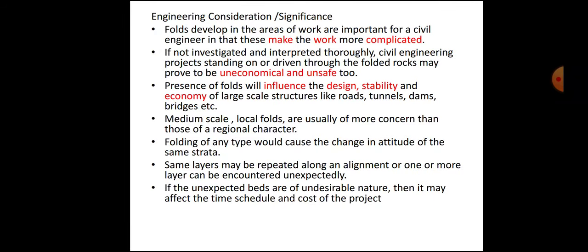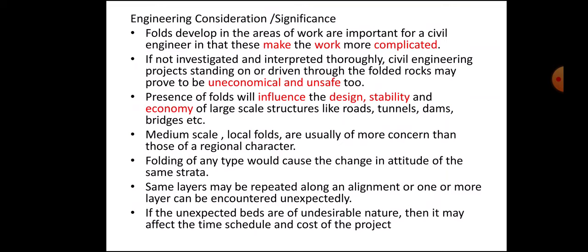Engineering significance. Faults developed in the areas of work are important for a civil engineer in that they make the work more complicated. If not investigated and interpreted thoroughly, civil engineering projects standing on or driven through the folded rocks may prove to be uneconomical and unsafe too. Presence of faults will influence the design, stability and economy of large scale structures like roads, tunnels, dams, bridges, etc. Medium scale local faults are usually of more concern than those of a regional character.